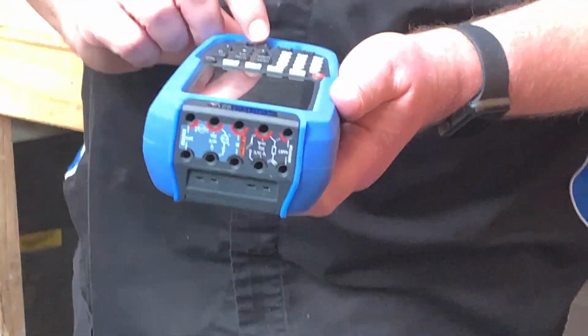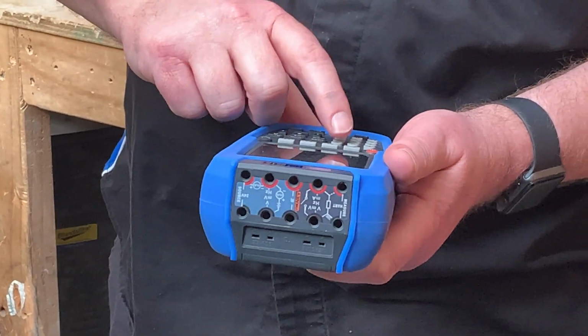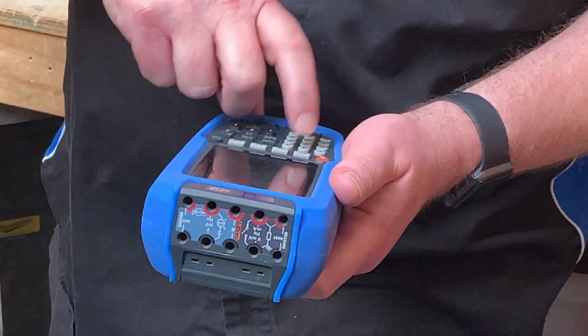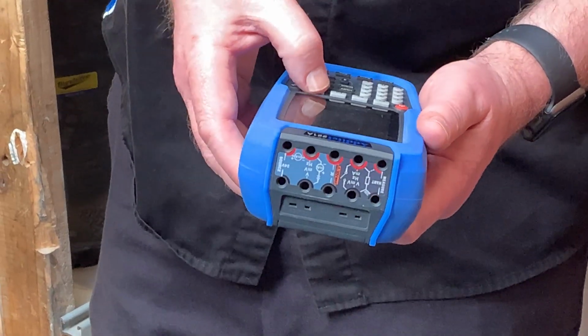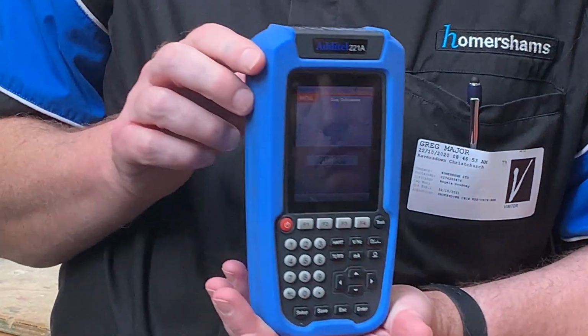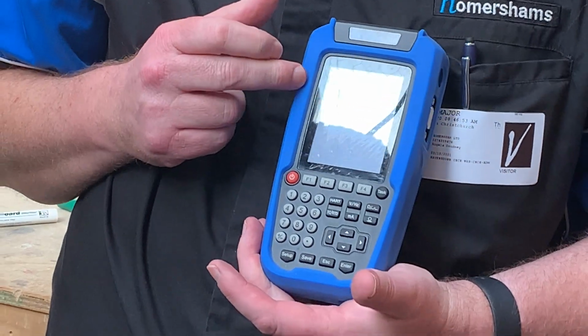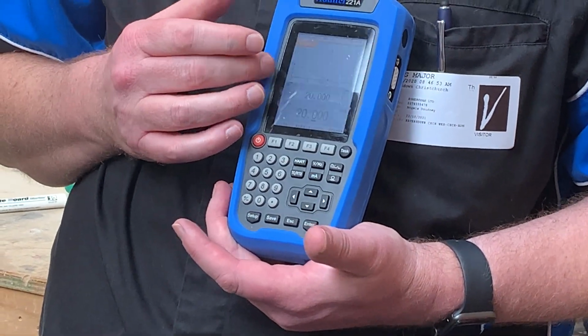Then it goes to 12 milliamp, the halfway point, and we're seeing on the display 13.5 milliamps, and we accept that. And then at 20 milliamps, we're seeing 20 milliamps. Now it's drawn you a graph of what the result of that display is.